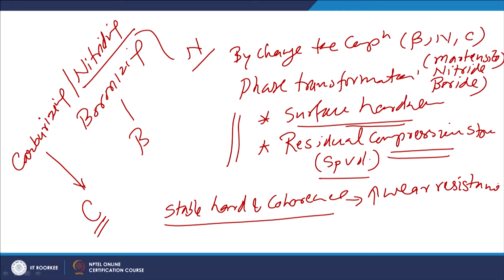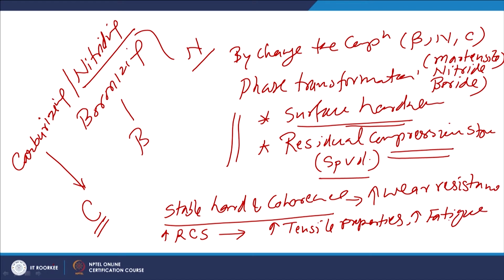On the other hand, development of the residual compressive stresses also increases the tensile properties and the fatigue resistance, because the severity of the external tensile stresses is reduced. So, the fatigue strength is increased.